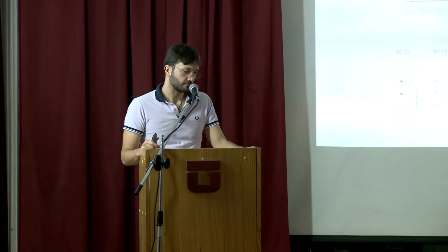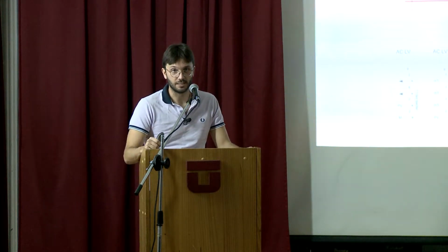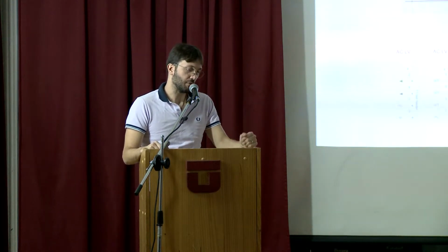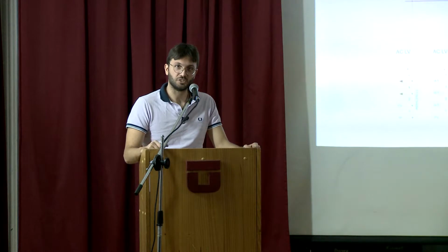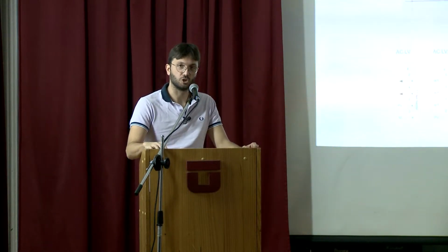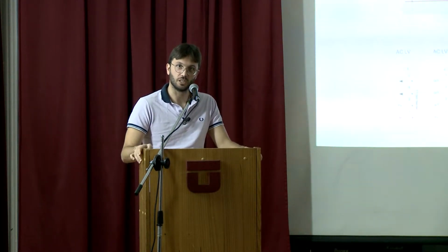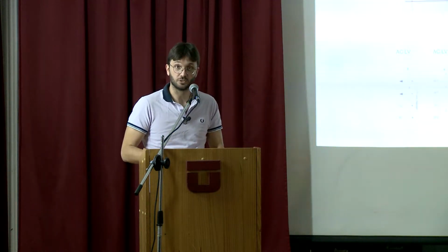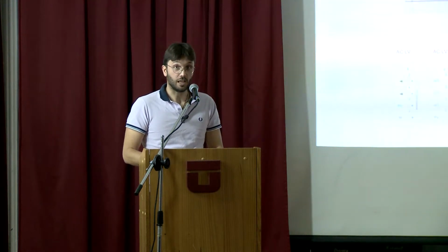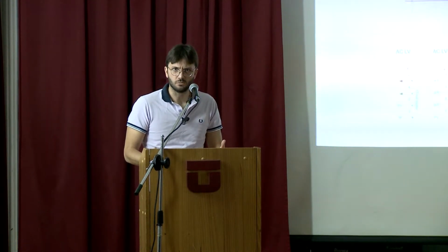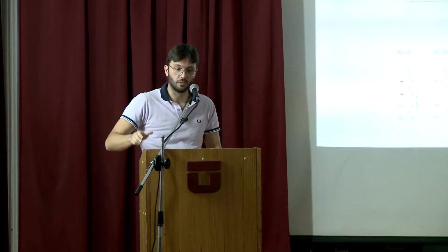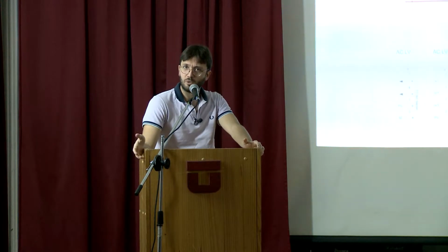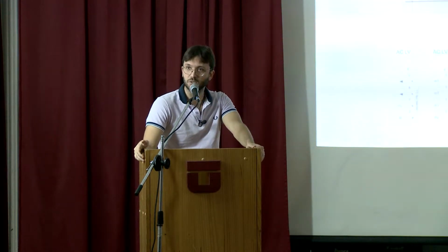Now, I'm pretty sure that everybody that has ever realized a grid-connected converter, coming from, I don't know, the undergraduate studies where we are told that the grid is a sinusoidal voltage. First time I connected the oscilloscope and I saw this trapezoidal voltage, more or less, very, very flat top. Then I went to my supervisor and I told him, hey, is there a problem with the oscilloscope? Because it's not sinusoidal.